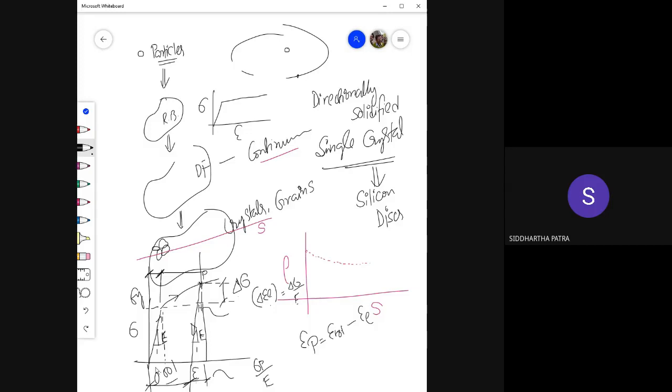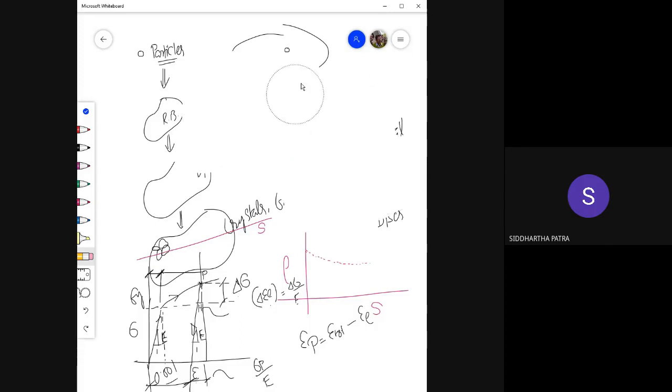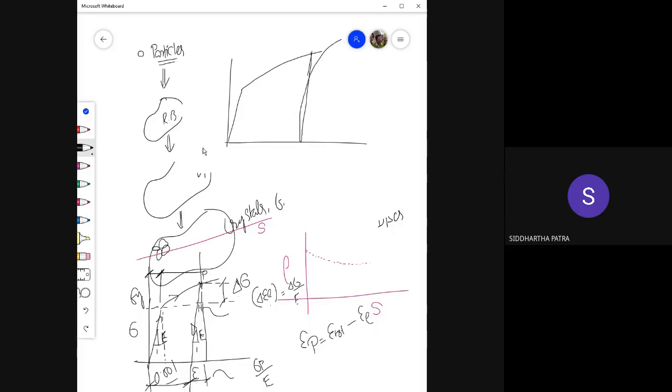Again, all of this is a model. All of this is a model that simplifies the math. To be frank, this is not exactly how material behaves. It behaves very close to that, but this is not exactly how it behaves. For example, when you unload, the slope is exactly not the same, first of all. And when it reloads, it goes slightly left.